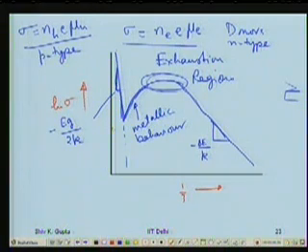So impurities have no effect really when the temperature becomes so high. The Fermi level has already come to the middle, and when that happens, there is no effect of the impurities present. Right? This is how the conductivity changes with N-type and P-type as a function of temperature.